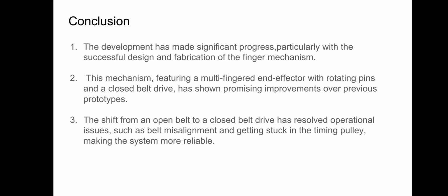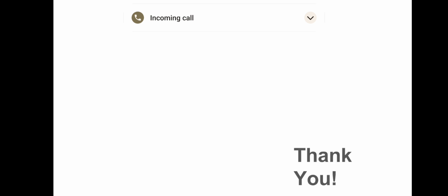This mechanism, featuring a multi-finger end effector with rotating pins and a closed belt drive, has shown promising improvements over the previous prototypes. In conclusion, I would like to say the shift from an open belt to a closed belt drive has resolved operational issues such as belt misalignment and getting stuck in the timing pulley, making the system more reliable. Thank you so much.